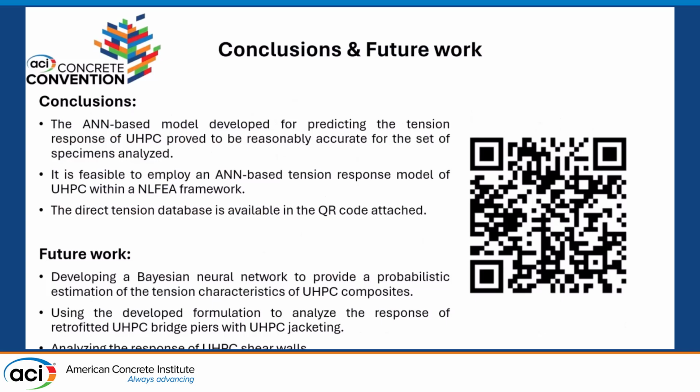So, in conclusion, the ANN-based model developed for predicting tension response proved to be reasonably accurate for the set of specimens analyzed, and it is feasible to employ an ANN-based tension response model for UHPC within a nonlinear finite element framework. Here, the direct tension database is available for whoever is interested.